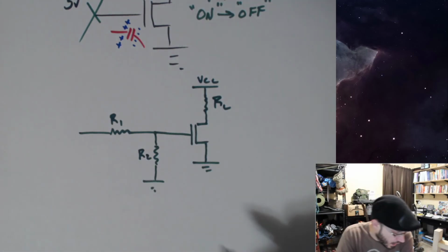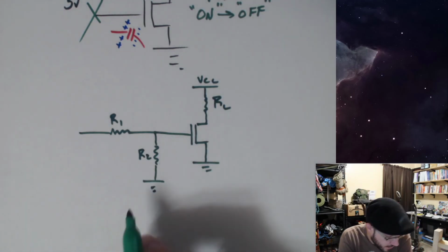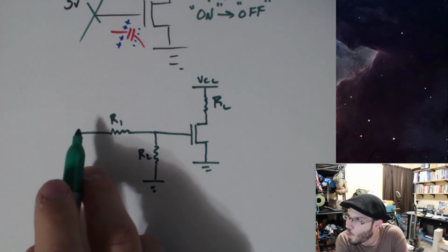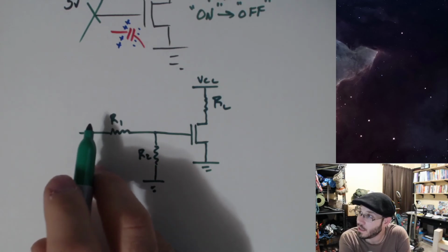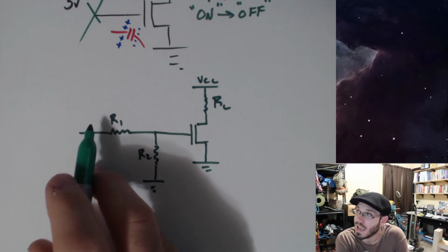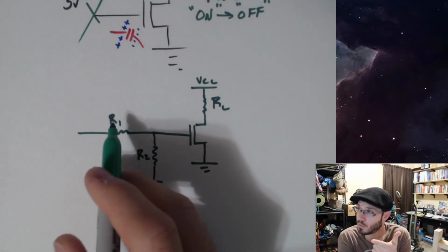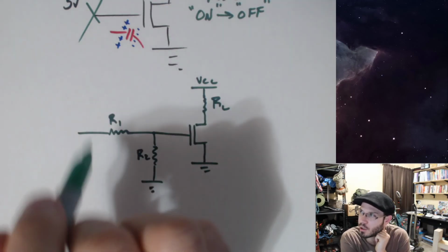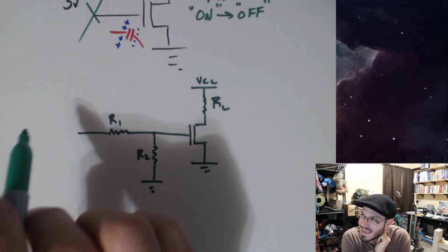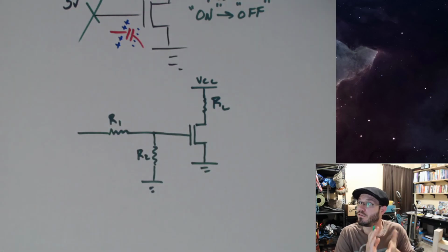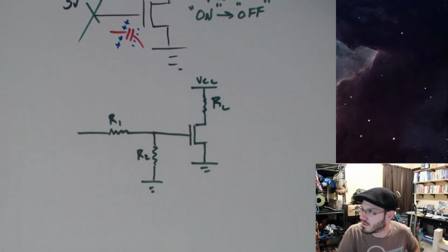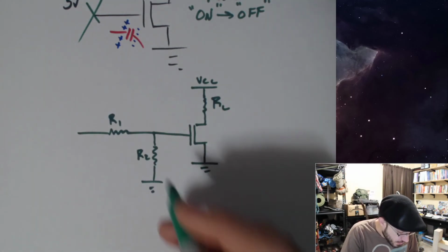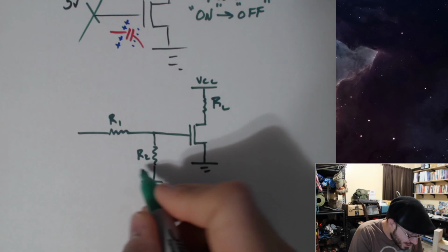Okay, so to leave this in a safe state in case something happens over here, or another good reason, maybe when your FPGA first starts up, when you initially power on your FPGA or your microcontroller, maybe those pins are not configured to the best configuration, and so for safety reasons, pretty good idea to do this.